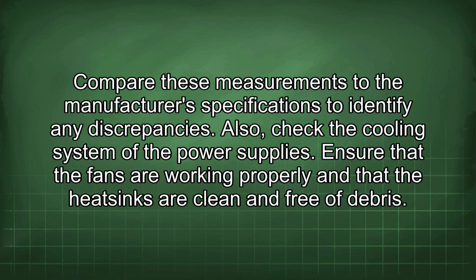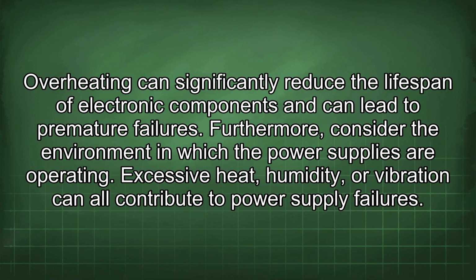Also, check the cooling system of the power supplies. Ensure that the fans are working properly and that the heatsinks are clean and free of debris. Overheating can significantly reduce the lifespan of electronic components and can lead to premature failures. Furthermore, consider the environment in which the power supplies are operating. Excessive heat, humidity, or vibration can all contribute to power supply failures.